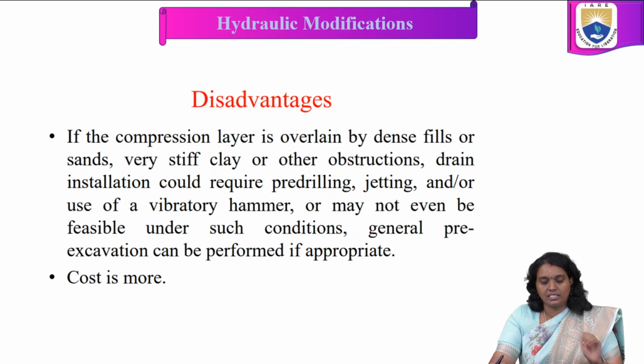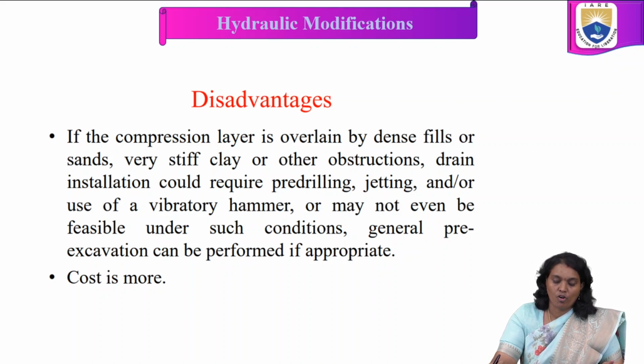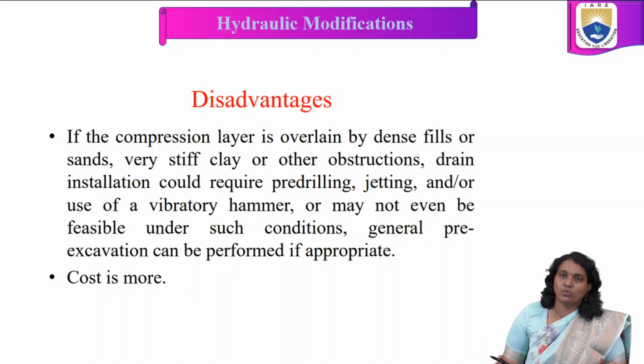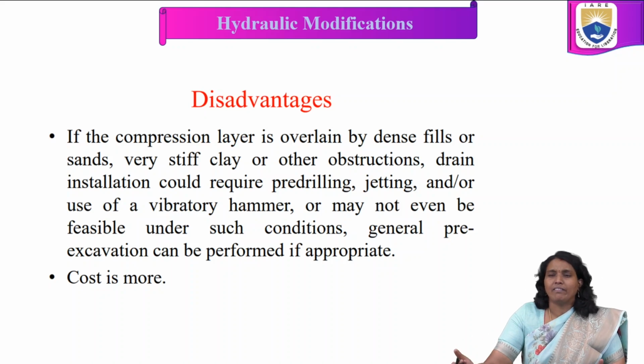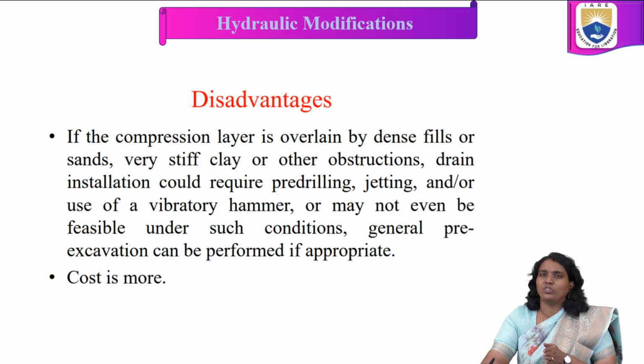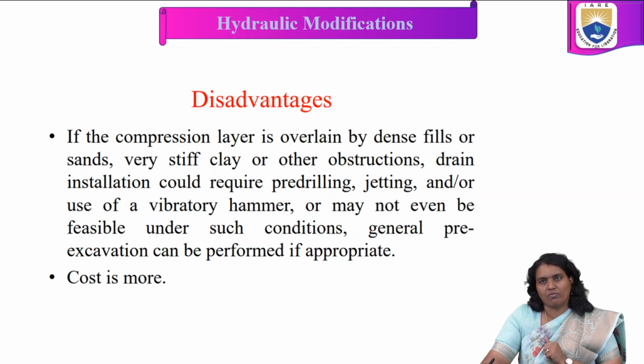In general, prefabricated drains can be used only at appropriate locations, and even if we overcome the obstructions and constraints, the cost is much more when compared to sand drains. So these are some disadvantages which we observed for the wick drains.